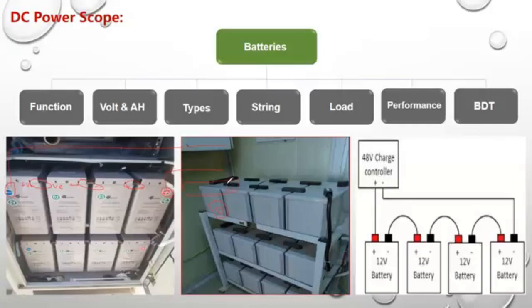But why positive? Because the positive parts are combined on it, but it is negatively charged. So here I did a reverse connection. Again, the positive goes to negative and negative goes to positive. And here I connected the negative 48 volt DC.